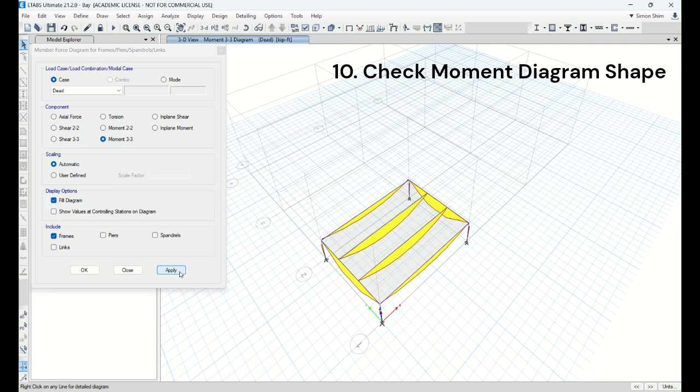That would be the compression with the tension. Now this is a bending moment. So I'm showing dead load and bending moment. We have some uniform dead load from the slab and steel, pushing down. So the moment when we draw is usually put on the tension side. So it's the bottom side. They draw the moment on the bottom, which is tension, right?